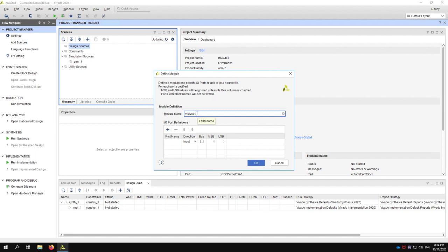And instead of my IC having a name like, I don't know, the 74LS00 or something like that, my module will have a friendly name that I will give to it called MUX221. And instead of having pins, so maybe I have 3 input pins and 1 output pin for a MUX, in this case, I have ports, and my ports have friendly names. So they're not numbered, but they have friendly human readable names.